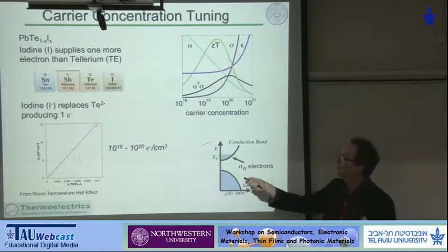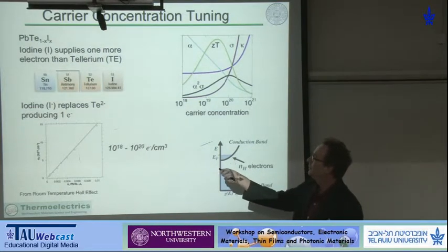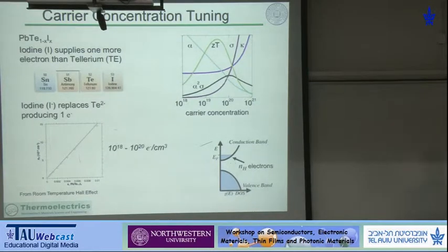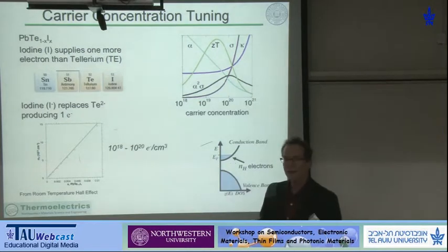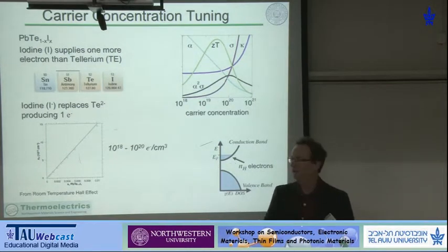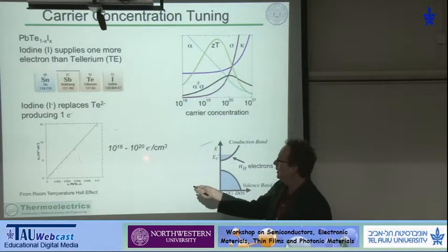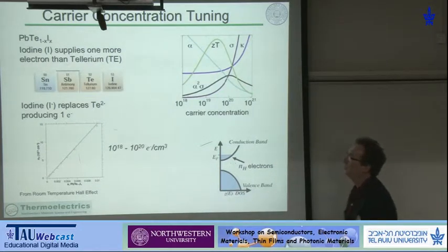We are putting so many dopants into our material that we simply count the number of extra electrons from the atoms that go in, from the extrinsic dopants, and that can, in many instances, simply correlate to the number of carriers, even up to 10^20, 10^21 carriers.